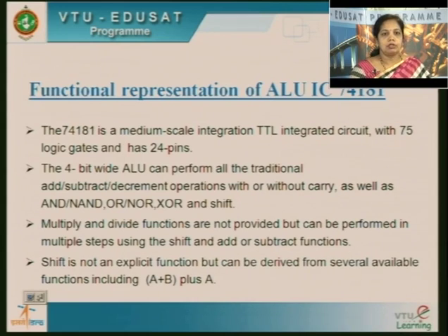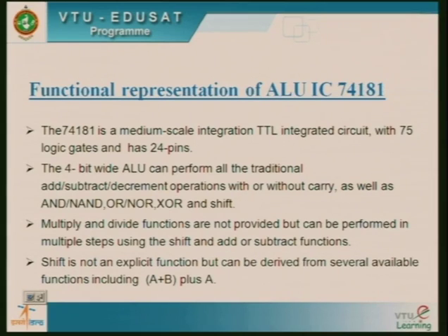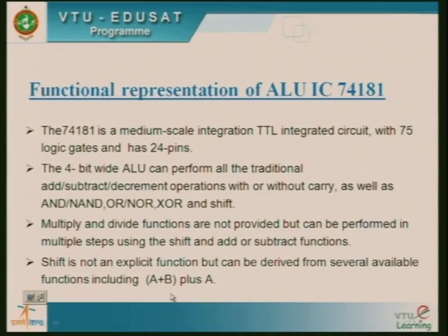We use shift and add for this operation, addition operations. Shift is not an explicit function here, but can be derived from several available functions, including A plus B plus A. So we can implement such functions using this 74181. These are the operations I can perform.